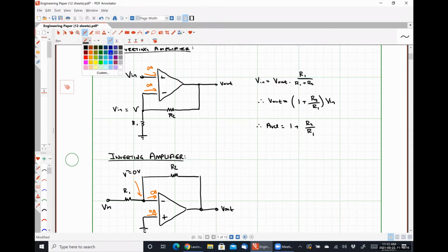So if my input voltage, let's just argue for right now that it's positive, but it really doesn't matter. But if my input voltage is positive, I should observe some current I flowing through resistor R1, and that current has to continue on and flow through resistor R2 as well, because it can't branch off and flow into the input terminals.